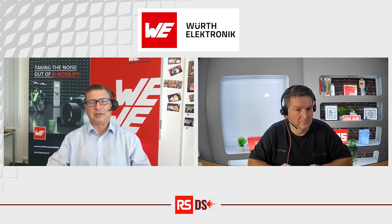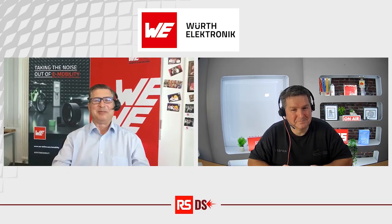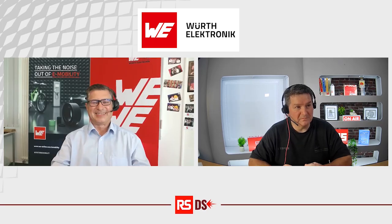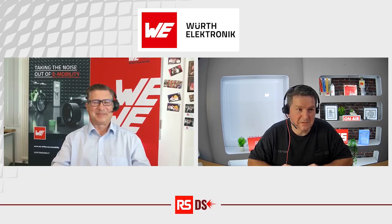It's like my children. If you tell the children the candle is hot, don't touch it, they will touch it. Same is EMI. You can tell them 1,000 times, they will still make the mistake until they burn their finger, and then you will start to improve your design by putting in some ferrite beads and the right capacitor with the right value. Yeah, that's a really good tip, actually, because the amount of times I've seen products fail EMC only to come back and have more cost associated with the product. So factoring that in right at the beginning of the design makes sense to me. That's really intuitive thinking, I think.